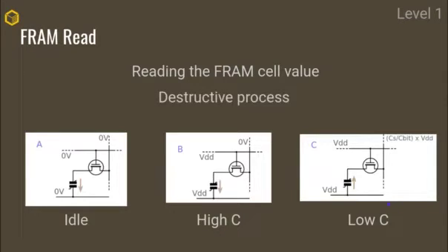Also, the problem with this is that I said that to write we would drive the line, but it's quite similar to the process of reading. And what happens in practice is that when we do the reading process, it's a destructive process where we slightly alter the configuration of our crystal structure. And so it is considered a destructive process. And so after every read, like in DRAM, we would want to rewrite the value that we read for it not to lose its state.